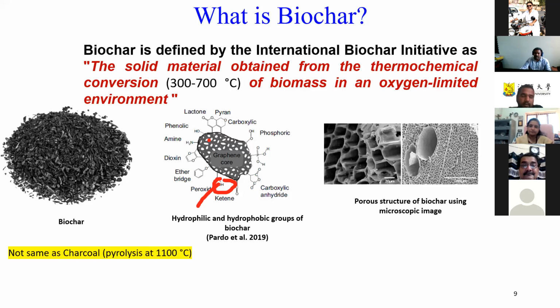So the soil-biochar aggregates I mentioned are very temporary in nature, depending of course on the water content. The other type of aggregate I talk about is the soil-root-biochar aggregate, which is formed because of root mucilage. Now, root mucilage is also cementitious in nature, but the effect is much less than the true cementation we are talking about. So the cementitious part in biochar is very minimal. You may even neglect it.